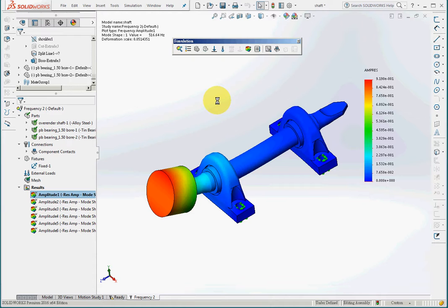For example, in static analysis, if you choose a gravitation of 9.81 and you draw a 3D body with a weight of 300 kilograms, and in another case you use a 300 kilogram force to replace the mass, in static analysis they are equivalent.